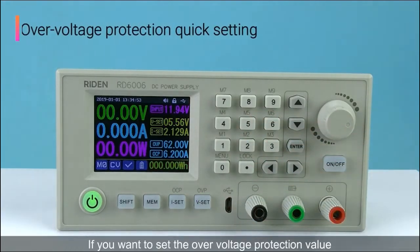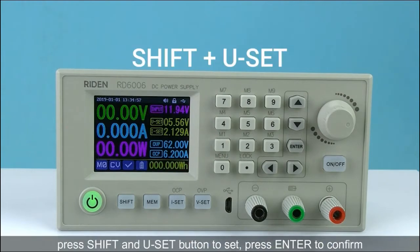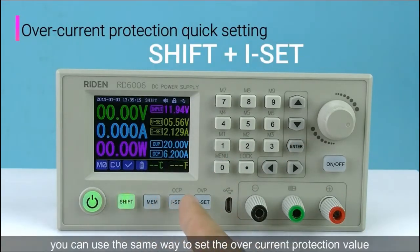If you want to set the over voltage protection value, press the Shift and VSet button to set. Press Enter to confirm. You can use the same way to set the over current protection value.